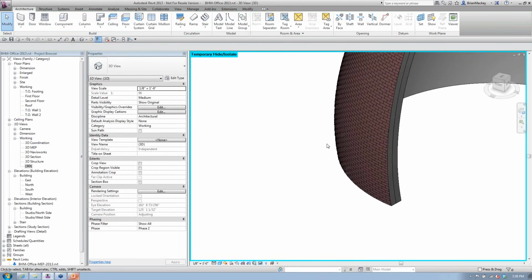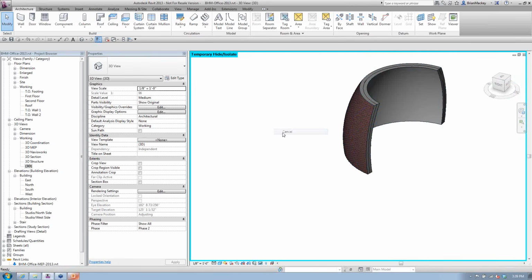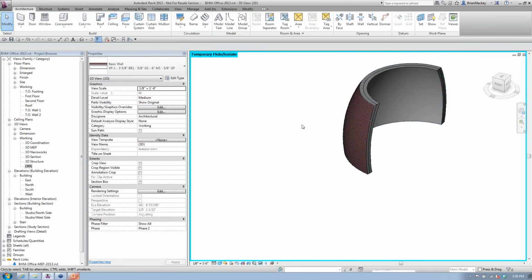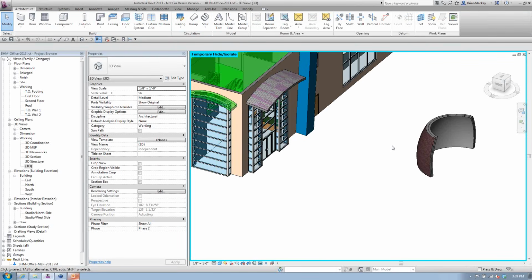Hopefully that works for you. And Karen, let us know if you need any additional explanation on that. Edwin asks, when you create a steel deck roof that is curved, you lose the deck profile outline when you draw a section through it. Any workarounds for this? No, unfortunately, you have to go in and use some sort of detail component that you could use to get the depth to bend around it. So yes, you are correct, Ed, that when we get into doing the curves, it wouldn't be roof, it would be floor, I'm assuming, you lose the composite metal deck profile.